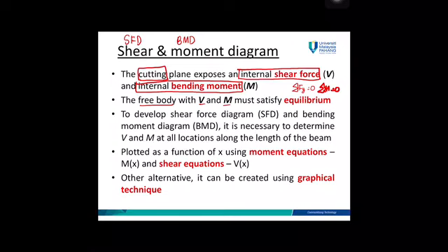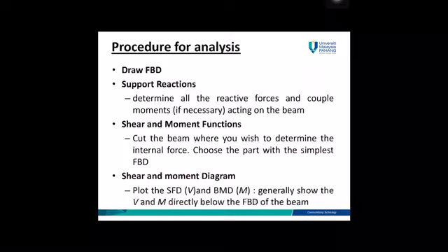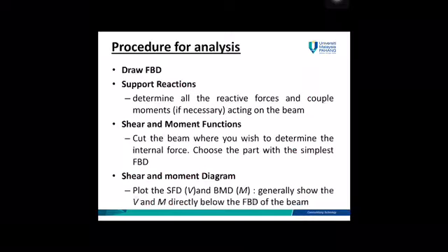Then you need to develop the shear force diagram and bending moment diagram by the moment equation and also shear equations. Or alternatively, you can use a graphical technique. So graphical technique I will teach you on the next subchapter. In this first subchapter, you will learn how to develop the equations. So this is a procedure of analysis.